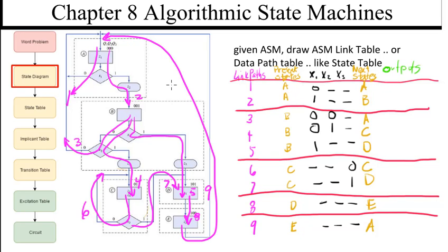And we have Z1, Z2, Z3, Z2, Z3, Z4, Z1, and Z3. All right, so we have Z1, 2, 3, and 4. Okay, in present state A, we have link path 1. Z1 is Moore, so it sets them both. In link path 2, it in addition sets Z2, which is Mealy. Remember, there's always zeros right here.